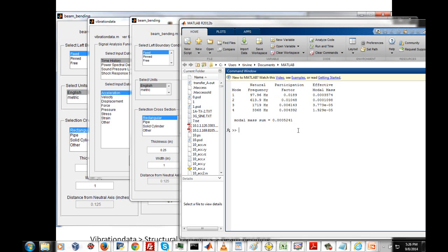And then as we include higher modes in our analysis, there's going to be a diminishing returns as to how much response is added by including each additional mode. Because as we go up higher in mode number, the participation factor is ramping down. Then here's the effective modal mass values, and we like to include enough modes to have about 90% or so of the total mass.